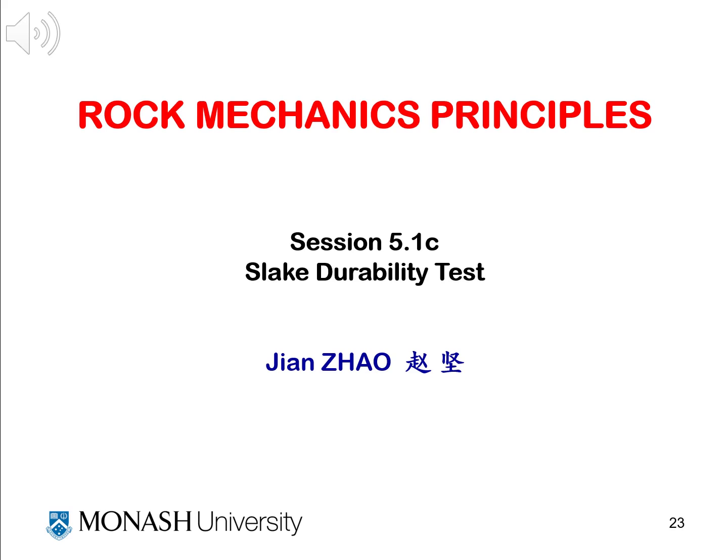We are now coming to the tests on durability of rock material. The test we conduct is called slake durability test. Slake durability test is designed to simulate physical weathering through drying, wetting, and physical contacting, and to measure the resistance to such weathering processes.